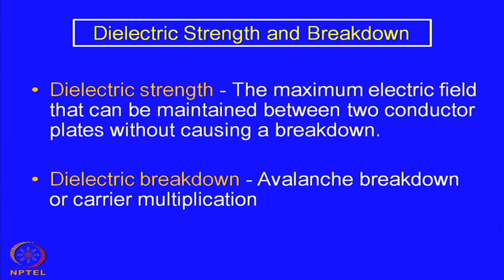So, there is a heavy short circuit and there can be an explosion, because suddenly a very high current will flow through the material because you have applied a very high voltage, and therefore there can be an explosion and a big spark and so on. So, that is what we call a dielectric breakdown. So, it is very important to know the limit of the applied field which the material can be exposed to. So, dielectric strength and the dielectric breakdown.